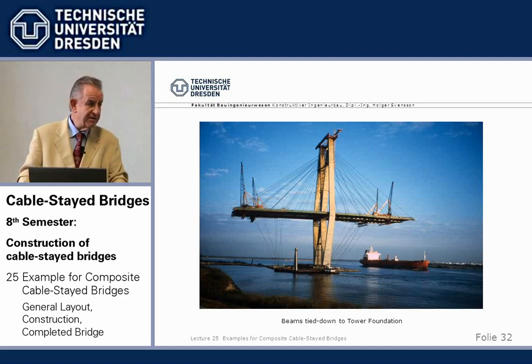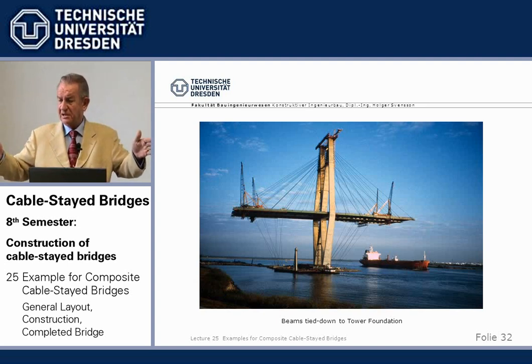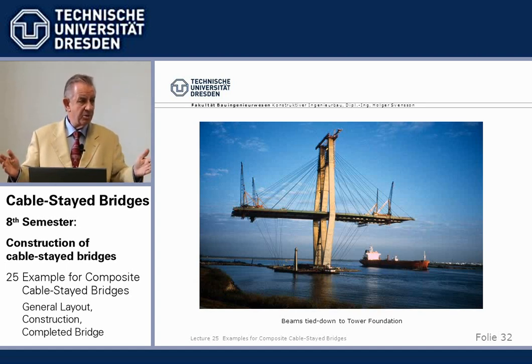We had at least 2 hurricanes going straight over during the 3 years of construction, and the bridge behaved exactly as expected, as calculated. The cantilevers made 1.5 meters plus minus movement when we were really far out. And everything worked fine.